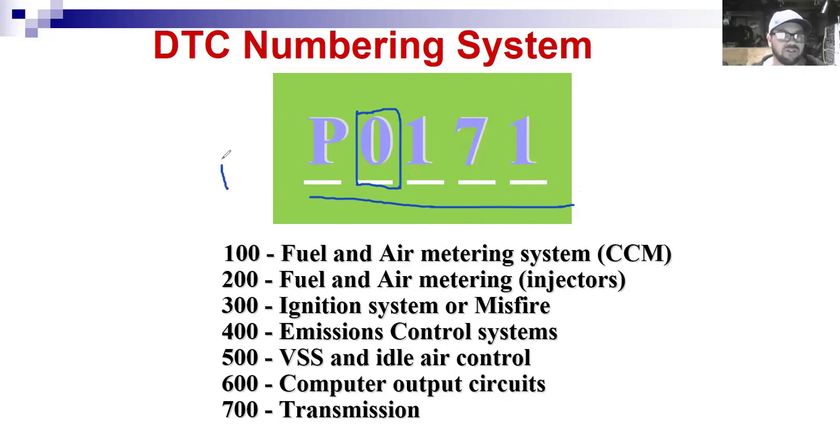Now, you'll notice that the vast majority of codes we've been focusing on, that we can really get good information on with generic data, are usually powertrain codes, because the goal with OBD2, of course, is to monitor those emissions over the life of the vehicle. And so it's the most robust in the powertrain area, right?